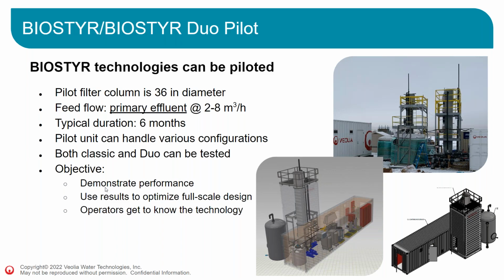This is designed so you can move the air grid inside. You can test DUO, classical, with or without denitrification, nitrification, whichever what is required on site. And the main objective when we're doing piloting of the Biostyr and the Biostyr DUO, it's to demonstrate the performances of the process. The results help to optimize the full-scale design, because the design is done on hypotheses that are usually applicable, but when you actually tested it beforehand, you can be more aggressive in the design because you know exactly where you're going.